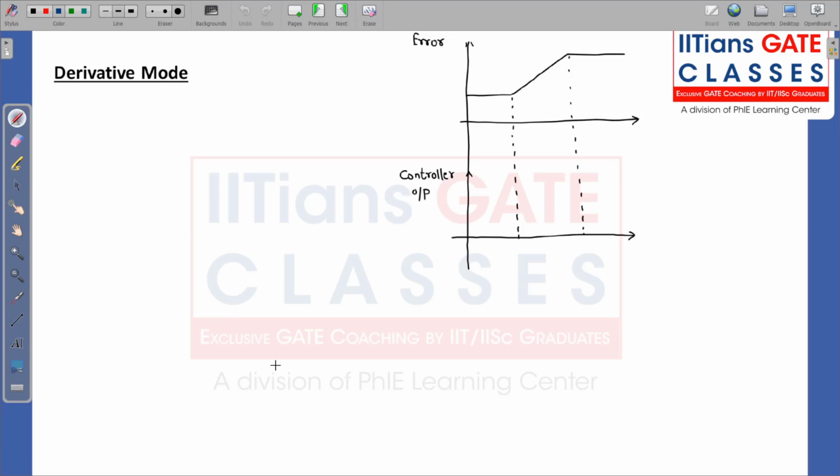So next we have over here is derivative control. In derivative control, we have the controller output directly proportional to the rate of change of error with respect to time. Now if I remove the proportionality sign, P of T comes out as Kd into de of t. So basically we have the derivative of the error, or rate of change of error.